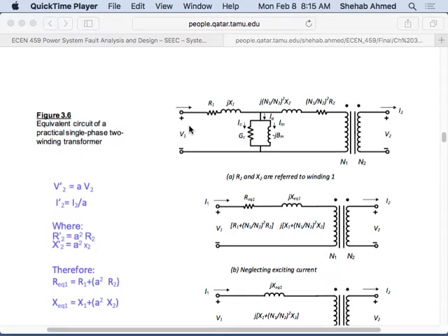So what we do is we don't want to generate short circuit current as such. We don't want to generate something above the rated current. What we want to do is generate rated current. Why do we want to generate rated current? So we place a short circuit here, and we put a voltage source here that we raise its value slowly until we reach rated current. If we reach rated current, what is this excitation current with respect to rated current?